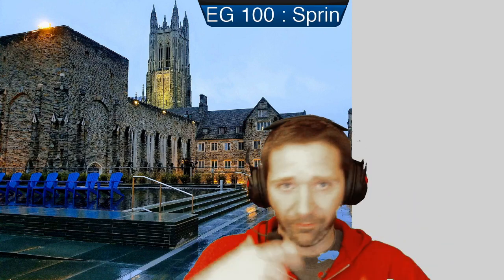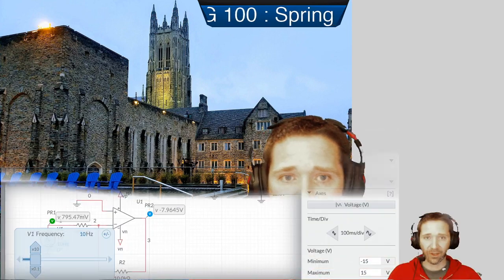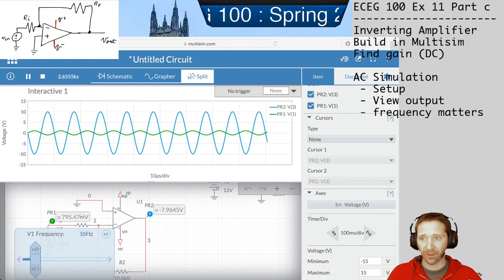You saw me create an amplifier. I made an inverting one. You have to make the totally different non-inverting amplifier. You are constrained to the resistor values that you can use. You have to do it choosing resistor values that we would get from that E12 series. So do some fancy combinations to get the numbers you need. But show me some screenshot like what you just saw. So what we just had was this with seeing the plots going at the same time, input and output. And that will work for that.